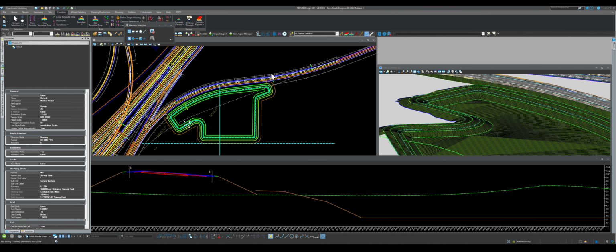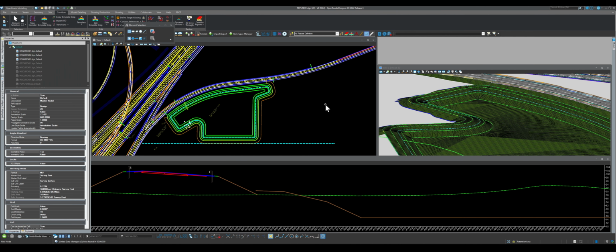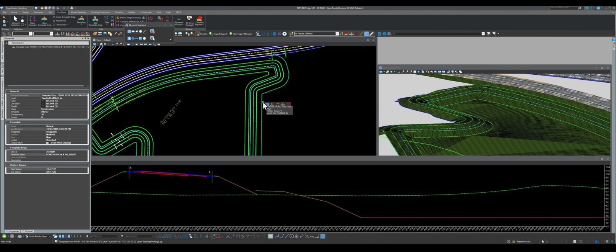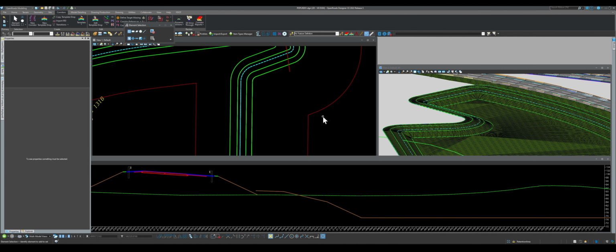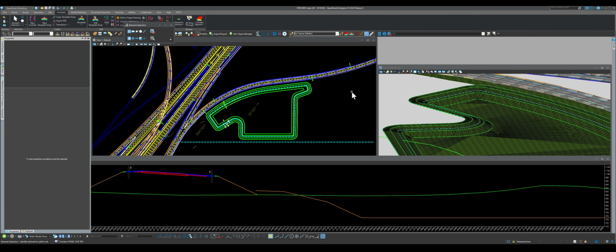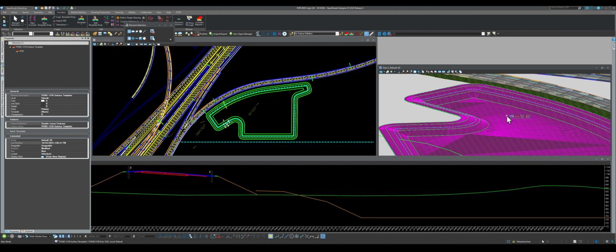So now we're gonna go finally to the templates, which is, I know most drainage people, they told me they don't use templates. But I would like y'all to get exposed to that. So the first thing we're gonna do, let's just delete the corridors and the templates. So I'm gonna strip everything out. And then I will click here and remove this surface template.